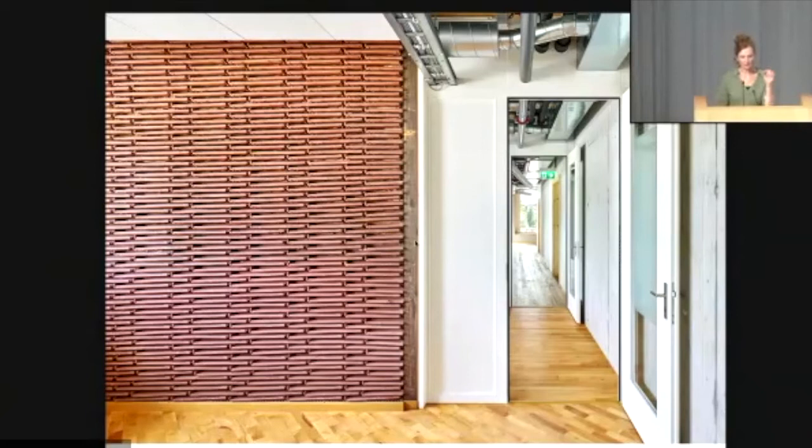And the plaster we used here was clay, so we can actually dismantle it. This is also an interesting thing because, as some of you might know, with brick walls these days, after the 60s, it's impossible to separate the mortar and the brick because the mortar is stronger than the brick. If you try to get the brick and the mortar apart, it's the stone that breaks and not the mortar. So this is also a thing that we should change.